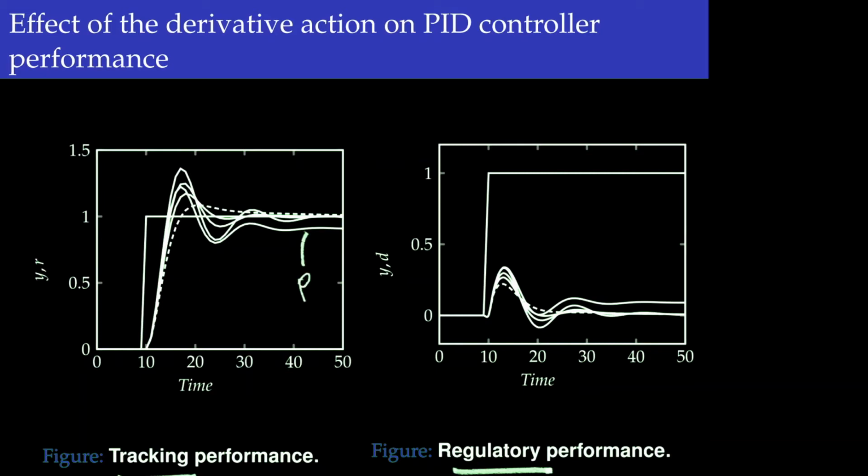We see that for proportional control, the final value is not at the desired value, meaning that proportional control will always result in an offset. For the integral control, this is the curve referring to PI, and we see a large oscillation of the process.